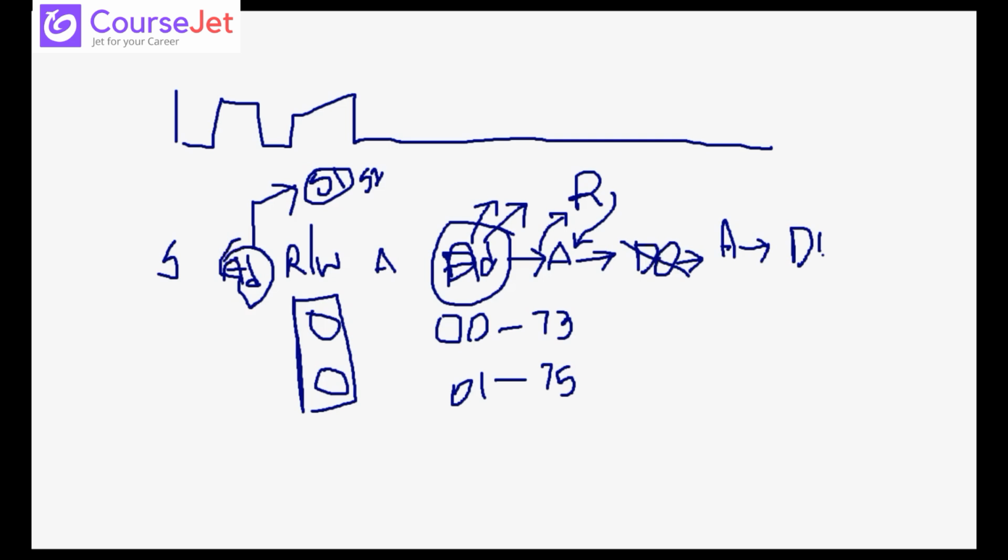See, here is how to select the frequency. The formula for selecting the frequency is CPU clock frequency divided by 16 plus 2 times TWBR times 4 to the power TWPS. Here TWBR is the bit rate register, a register where we are going to load a particular value, and TWPS is your prescaler. Prescaler is nothing but a value like 1 or 2.